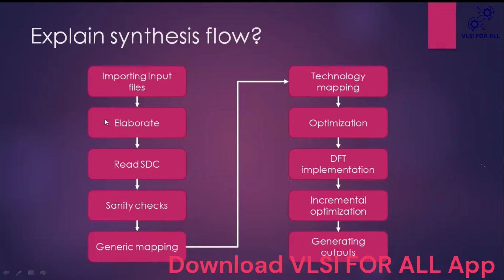Then we have to read SDC. What is SDC? SDC holds the guidelines for the design, timing guidelines. All our design has to meet this timing. For example, if there is a false path in the design, how will the tool know that particular path is a false path?